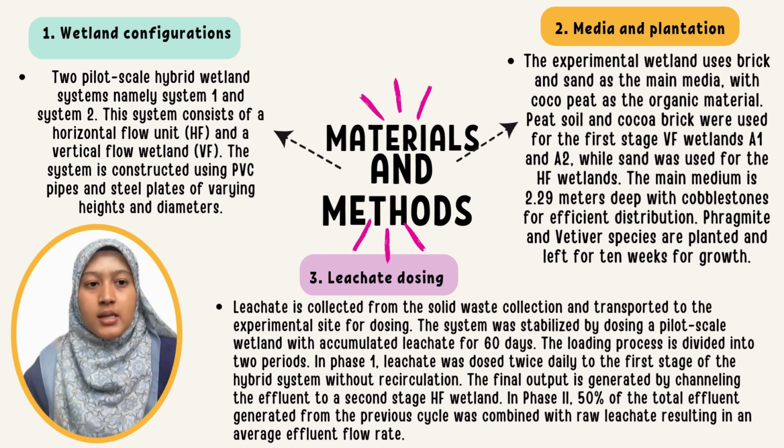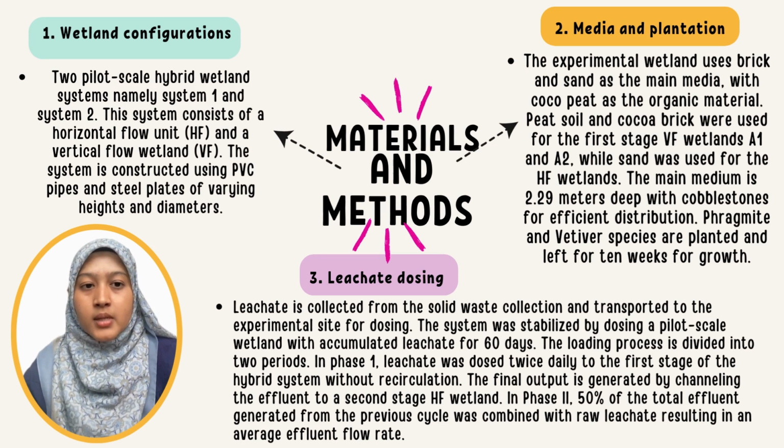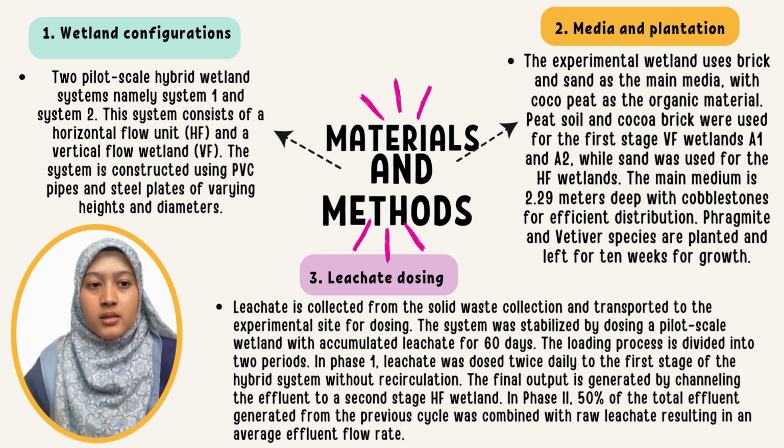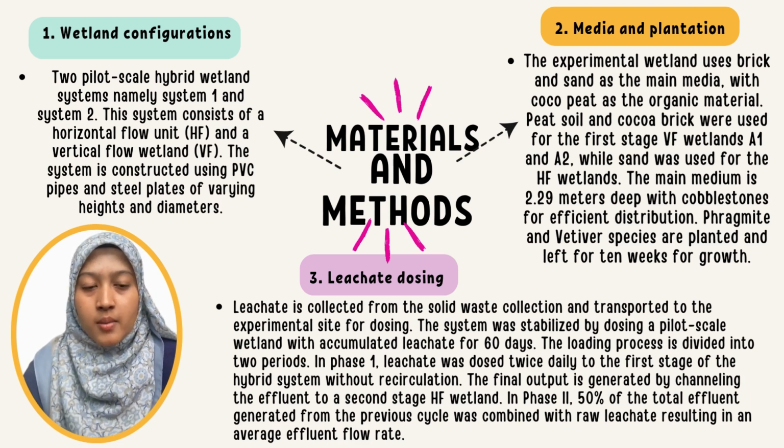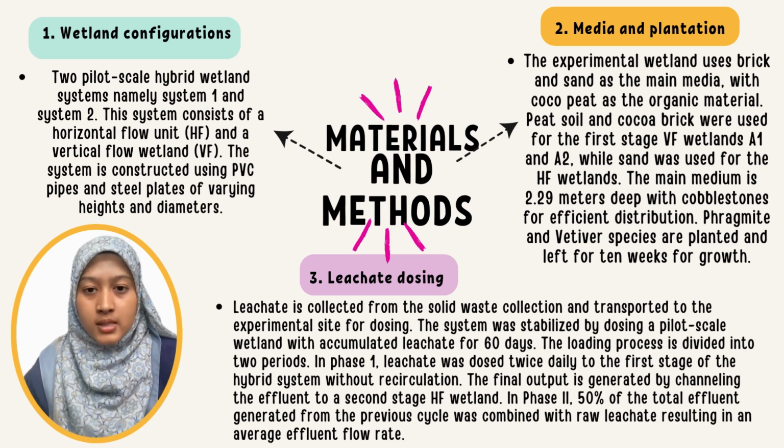Number 3 is leachate dosing. Leachate is collected from the solid waste site and transported to the experimental site for dosing. The system was stabilized by dosing the pilot wetland with accumulated leachate for 60 days.